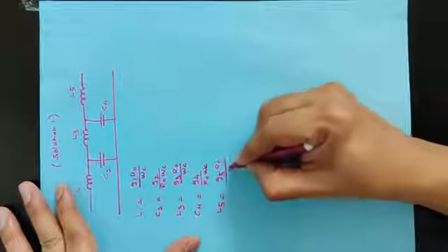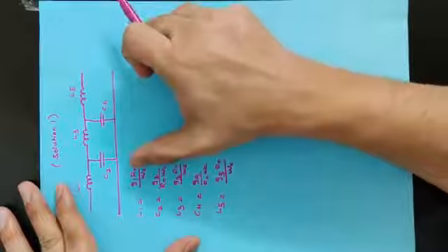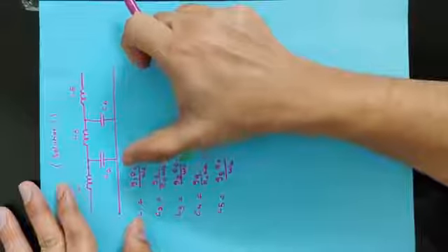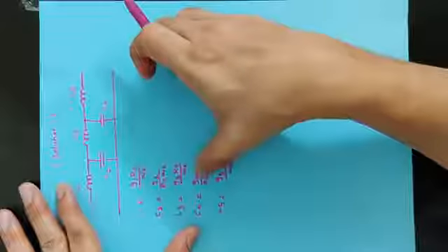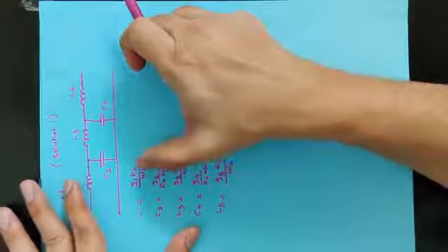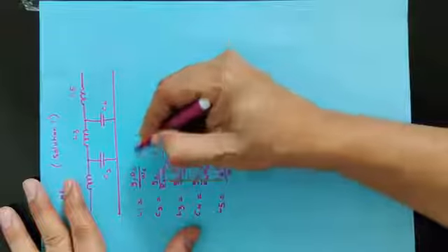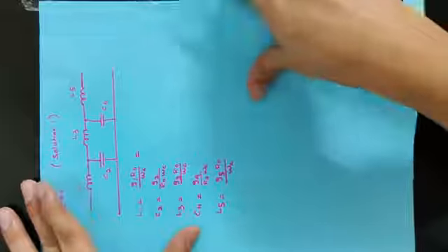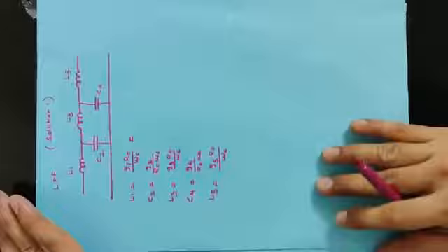So no need to memorize the formula, just remember this. For designing a low pass filter, if one has to calculate the value of an inductor, we have to multiply by R0. For the capacitor it will be division by R0, that is the characteristic impedance. And frequency scaling is always division by omega c. So we'll substitute the values of G1, G2, G3, G4, G5 that were calculated.